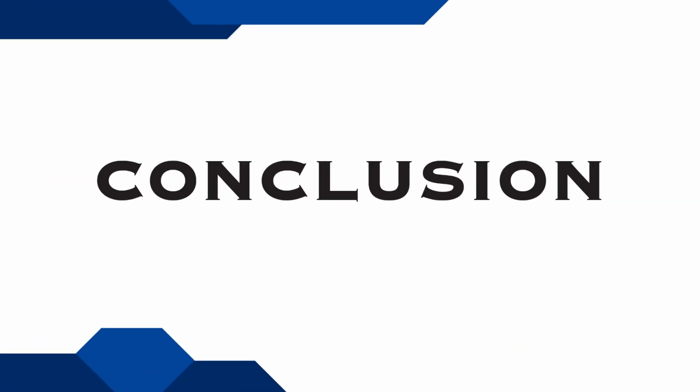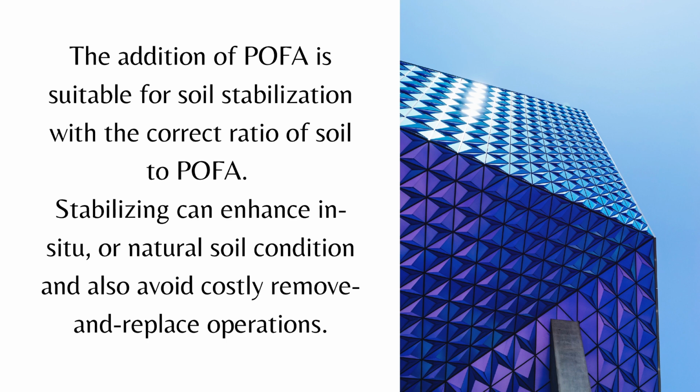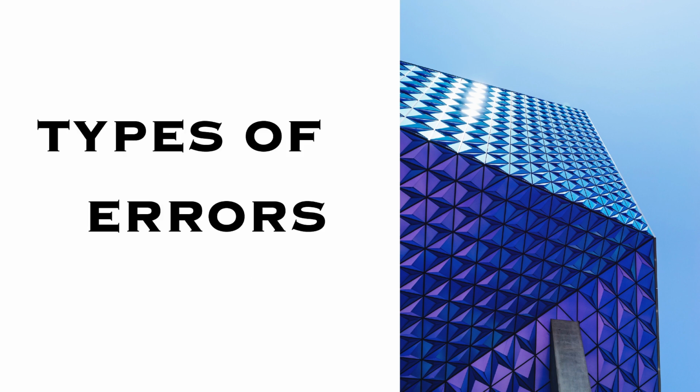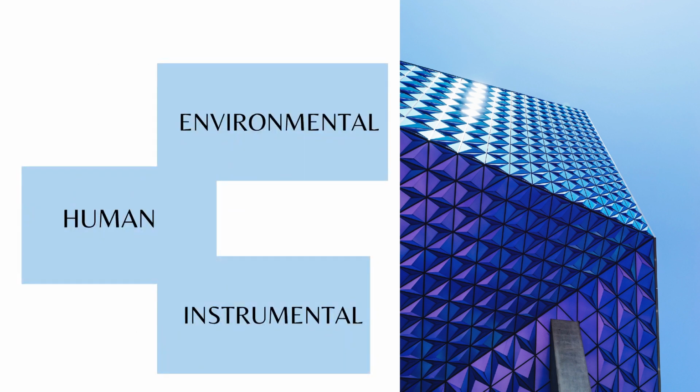Conclusion. It can be concluded that the addition of POFA is suitable for soil stabilization with the correct ratio of soil to POFA. In addition, stabilizing can enhance in situ or natural soil condition and also avoid costly remove and replace operations. In this test, many errors could occur, such as environmental, human, and instrumental error.